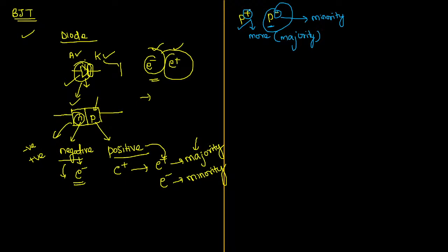Minus indicates decrement, plus indicates increment. In the same way, N plus means the layer carrying negative charges has a very high doping concentration of negative charge. Suppose I represent it by N minus, then automatically, sir, it's very easy now. Minus means decrement. In a particular layer, negative charges are available, sir, but its count is very less. That is called minority negative charge carriers. So this is majority negative charge carriers. This is how we consider the effect of electrons and positive charges wherever it is required.